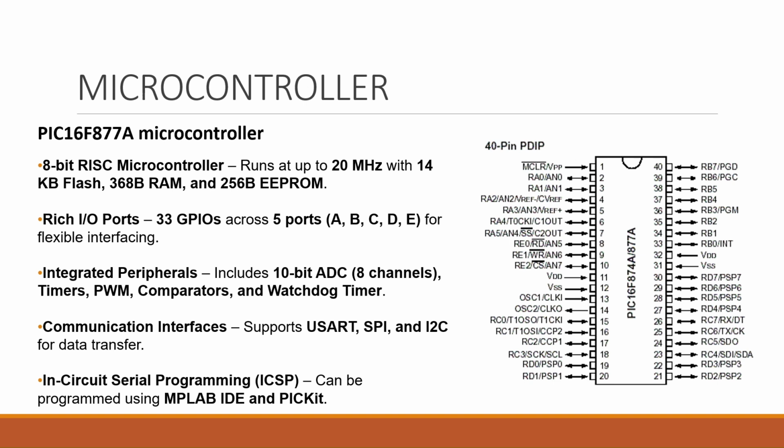The integrated peripherals include a 10-bit ADC, that is an analog to digital converter, and also timers, PWM, that is pulse width modulation, comparators and a watchdog timer. For communication interfaces, it supports USART, SPI and I2C for data transfer.